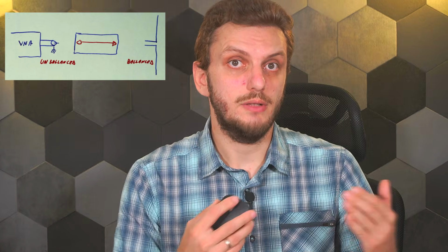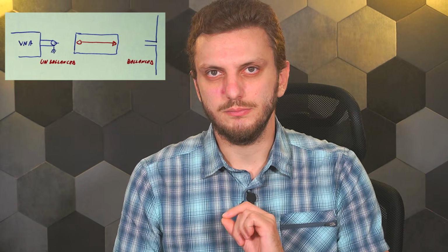Next, it's time to verify these claims and principles with some experiments. For that, I will be using a light VNA to measure a 35 cm long dipole's impedance, an antenna that could be used in the 70 cm ham band. But before starting that, it's important to remember that the dipole is a balanced load, and the VNA has an unbalanced input. To make a correct measurement, we need some sort of adapting circuitry in between the two, a balun.